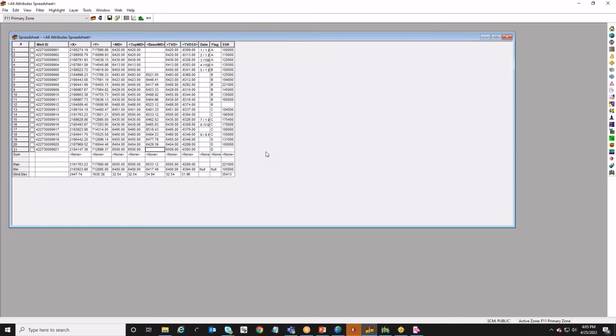of that didn't import. So now I've got that in here, date, flag, and EUR values imported in directly from my spreadsheets. Those attributes are now in there within the particular zone, and their data is in there. So a couple of these were left blank. They were left blank in the spreadsheet. So it goes through there and automatically, oops, I accidentally clicked in there and it populated data. I didn't want that. So that data knows to skip over the blank information and not bring anything in there from your spreadsheet whenever you import that information.